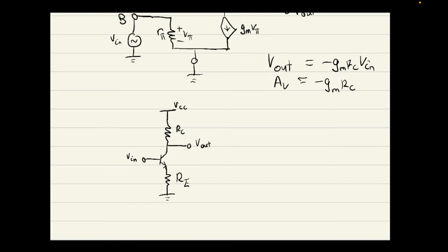So, does anyone want to take a guess at what this does? So this resistor over here, attached to the emitter, is called a degeneration resistor. It introduces negative feedback. You don't need to know exactly how it does that, but it stabilizes your gain and also makes it less dependent on gm and more dependent on your circuit parameters. I'll go over feedback in a couple of sections.